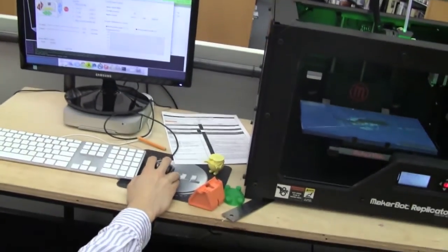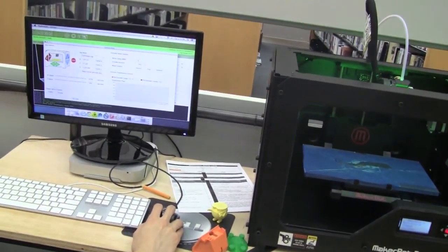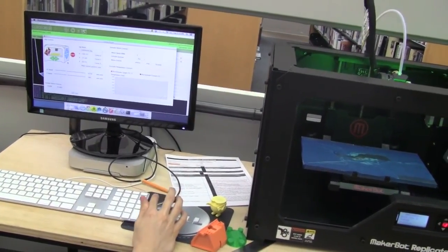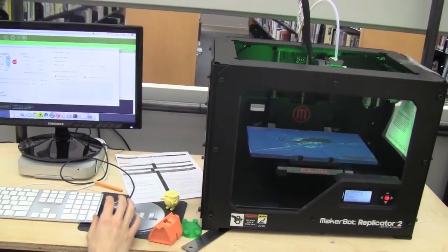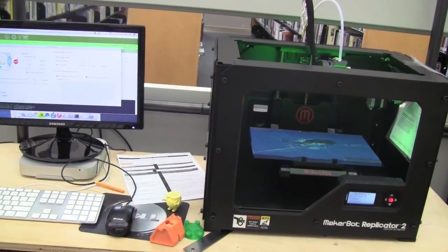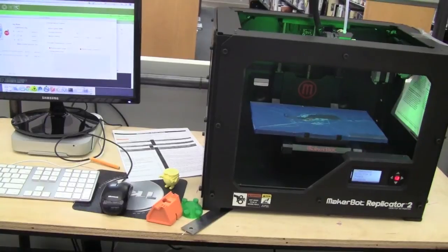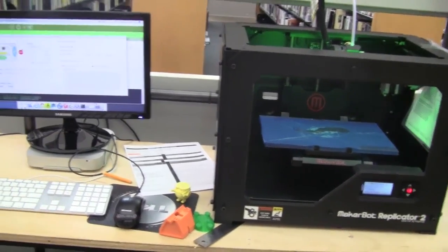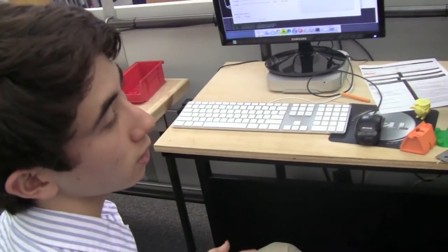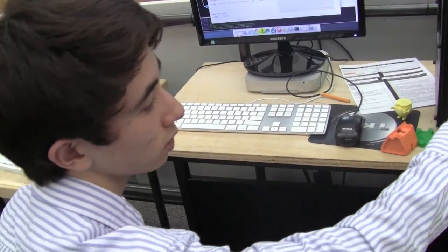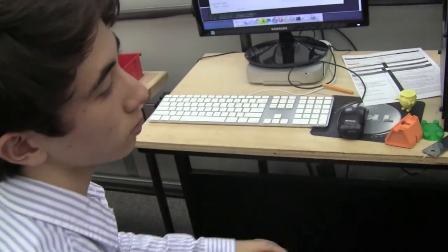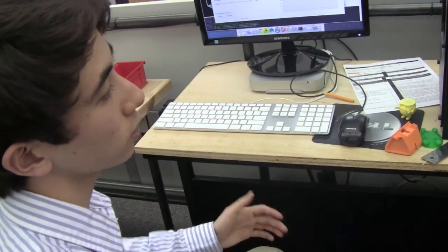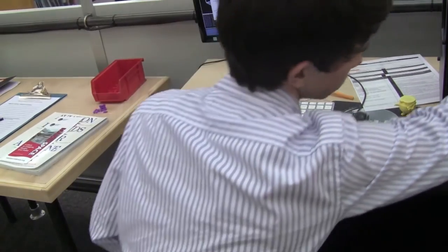This could be useful if you just finished a print and you want to get everything out of the way. Sometimes if you're in control panel or you finish printing, the motors lock themselves. When I say lock, it means they're just waiting for computer input, so you can't push it yourself, which means the motors are active. If the motors aren't active, then you can manually push the extruders around. I wouldn't suggest you manually push the platform down, since it's on springs for calibration, and you might uncalibrate it a little by putting too much pressure on it.